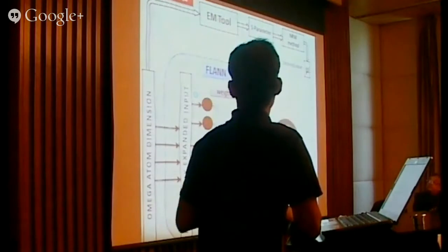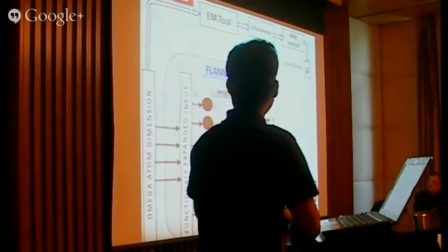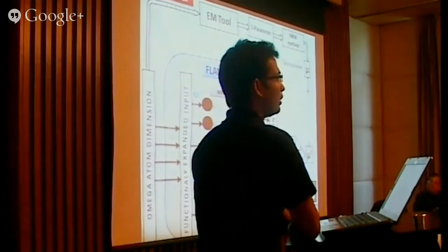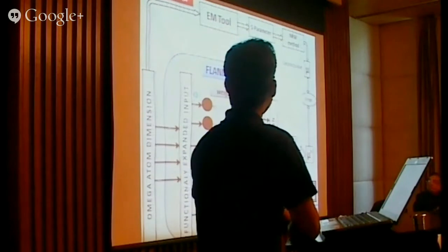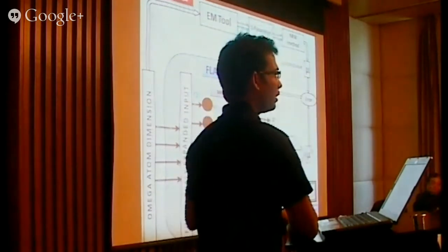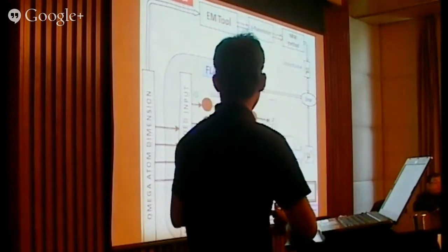That follows the mapping technique, and the mapping technique gives us the equivalent SRR model, from which we use the Lorentz model to get the permeability, which is the approximated result. Then we calculate the error and adjust the weights of the mapping tool. Here we have used the mapping tool as a functional link neural network, an alternate model to the multi-layer perceptron neural network. Why have we used FLANN?